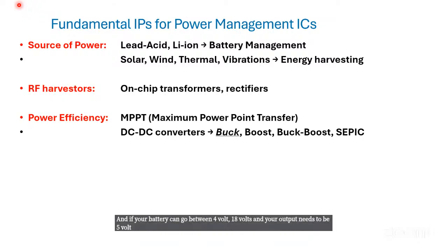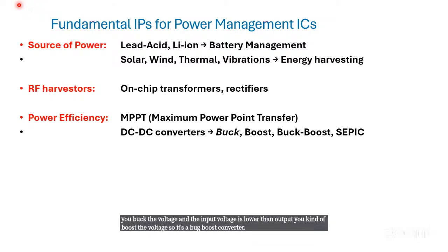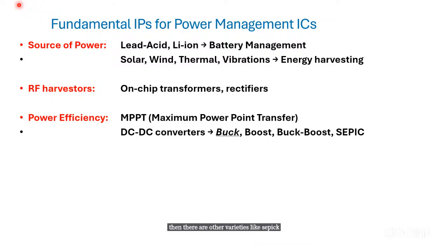Then you need a buck-boost. When the input voltage is high, you buck the voltage. When the input voltage is lower than the output, you boost the voltage. So it's a buck-boost converter. Then there are other varieties like SEPIC and flyback converters. All of these are possible.